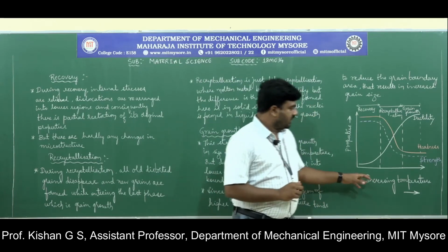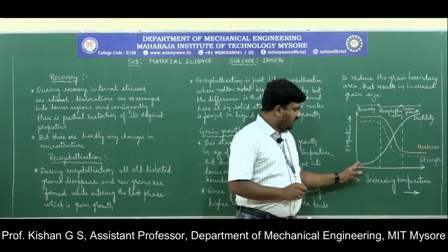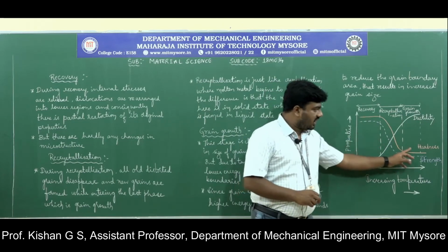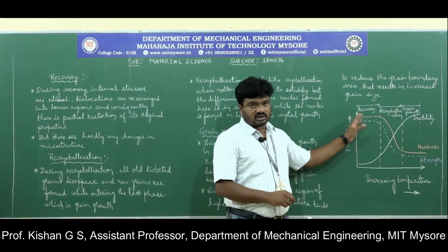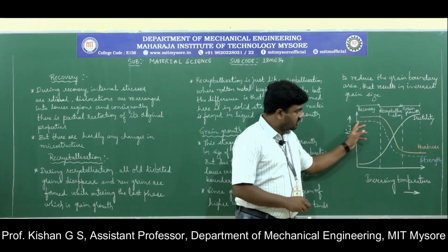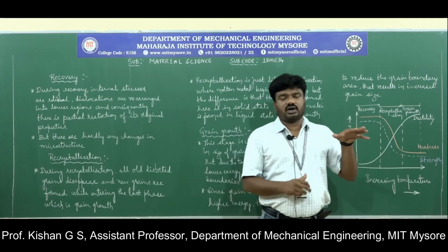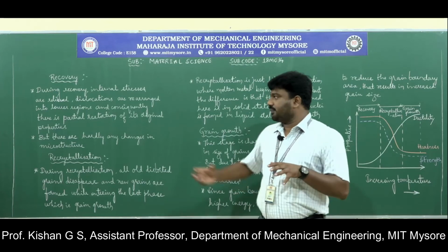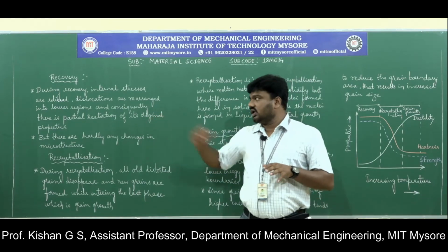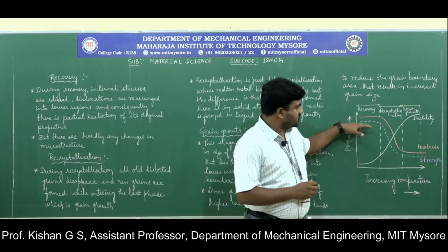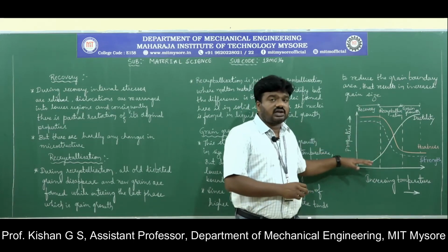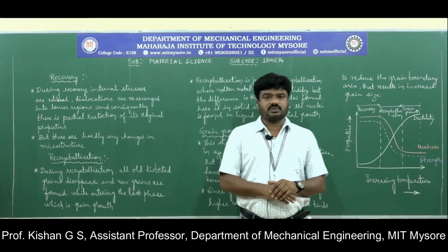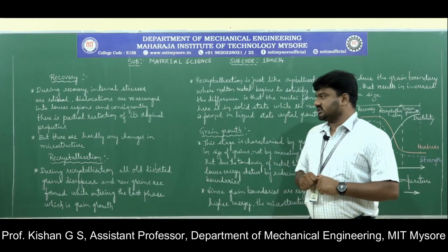You can observe here that in the recovery stage, there will be a minimum increase in the ductility of the material, whereas the strength and hardness, as you can observe from the variation in the colored chalk, almost remain the same. That means the microstructure will not change, whereas partial restoration of its original properties is achieved. That goes with the strength and hardness of the material, but the ductility will vary in the recovery stage. Next comes the concept of recrystallization.